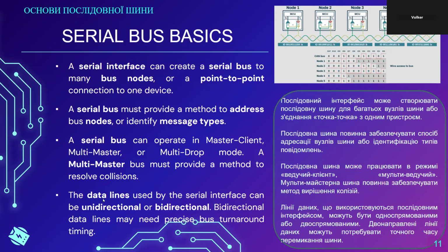And the problem with this is that if the system is bidirectional, it's also sometimes called half duplex. If it is bidirectional, then the master is issuing a command, and it is occupying the bus while it's actively driving the bus in both directions. It is issuing a command or a request to a slave, and the master must relinquish the bus, must turn off its driver before the slave starts transmitting.